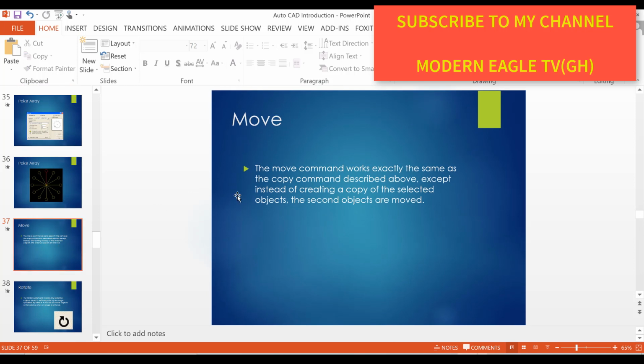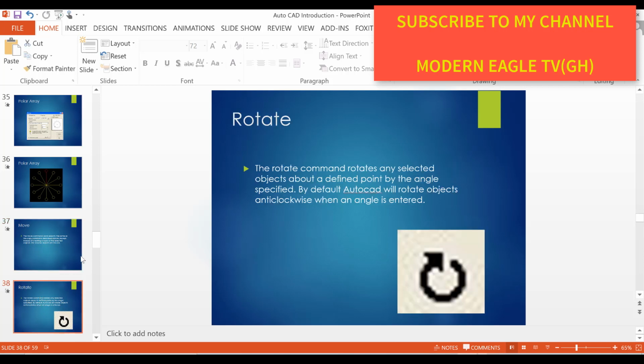Move command. The move command works exactly the same as the copy command described above, except instead of creating a copy of the object, the selected objects are moved. Rotate. The rotate command rotates any selected object about a defined point by the angle specified.